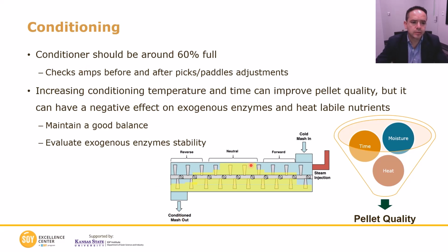Also, as I mentioned before, if you don't have a VFD, you can change the angle of the paddles. And a good idea is that every time you make a change, you should monitor the motor load. Because if you make a change and then you are retaining the feed in the conditioner for a longer time, your motor load is going to go up.